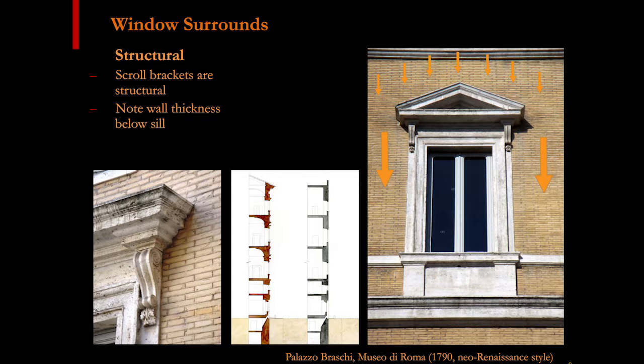So this is the section through this building. This very thick wall here, putting it into each side at the jamb, allows them to make this wall right here very thin. So you can see that wall's very thin here. And that's really important because if that wall were 3 feet thick, you could never get to that window or open it up. Our arms aren't that long, right? So structurally, they're enabling that by using the lintel or the arch in some cases to get that load over to the side and allow that wall to be thin rather than thick.